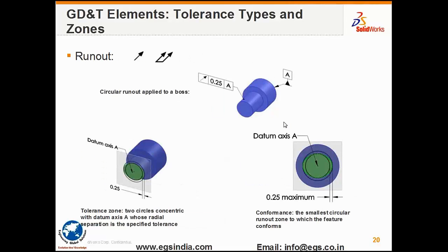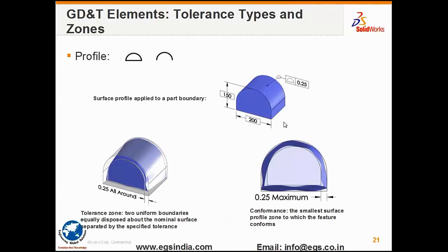Runout, as you can see, is a measurement specification that we try to comply with at the design stage using the runout schema. It is necessary to have datums so that we can inspect it according to the inspection procedures provided for. Similarly, for profile, you have it with and without datums. If it is without datums, it is form control. If it is with datums, depending on the restraints available with datums, it could be orientation control and or location control in addition to size and form.